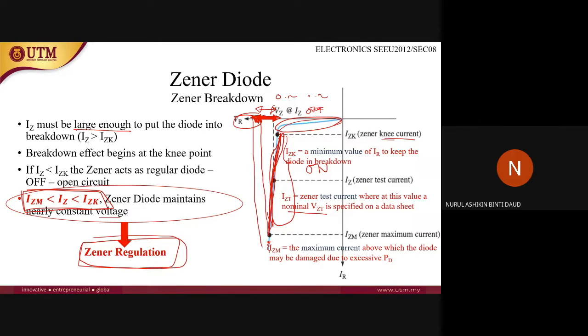Usually inside the circuit, together with the Zener diode, we will apply a resistor to protect the Zener diode, so that the voltage is not at maximum, to make sure that the Zener diode will not break. We will look at that later. Together with the Zener diode, there is a resistor. There are various kinds of resistor, which are variable resistor and fixed resistor. So the Zener diode will not operate alone. It will operate with a resistor to control the current, to control the voltage or current.